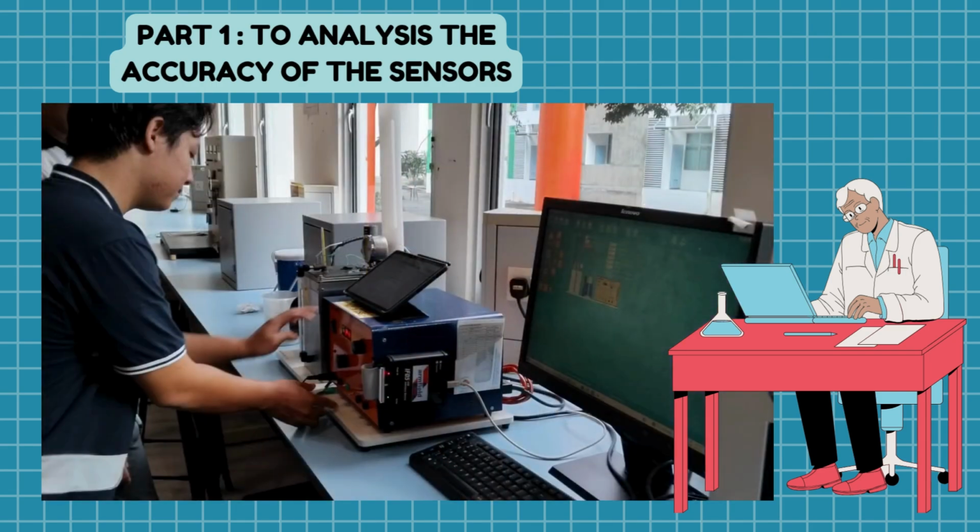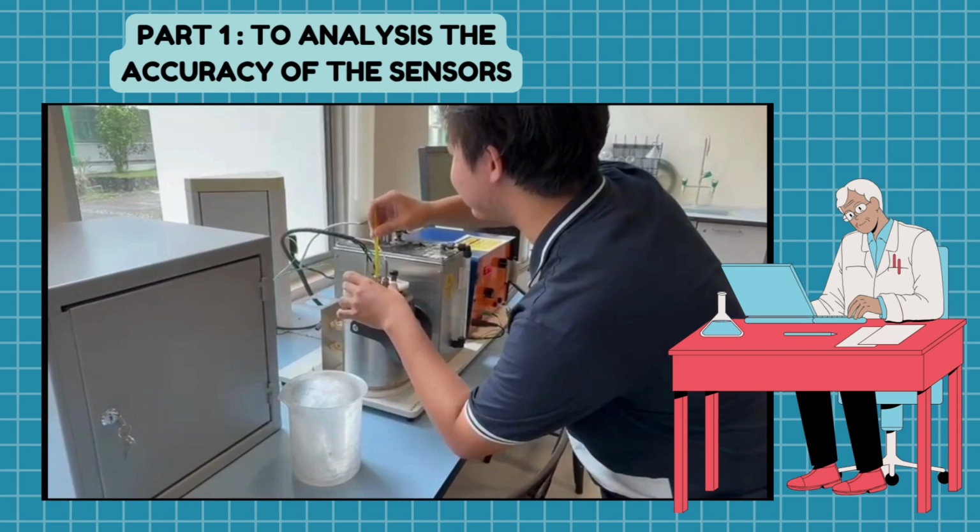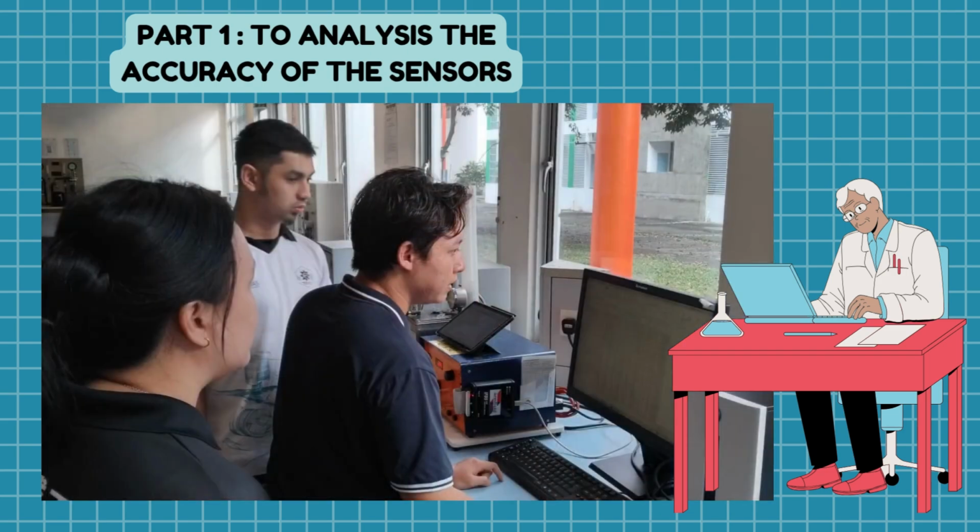Second step is to connect each sensor, thermocouple, RTD, and thermistor, to the data acquisition system or digital multimeter. Place the sensor in the reference temperature medium. Then, record the sensor output: voltage for thermocouples, resistance for RTDs and thermistor, and convert to temperature using the appropriate